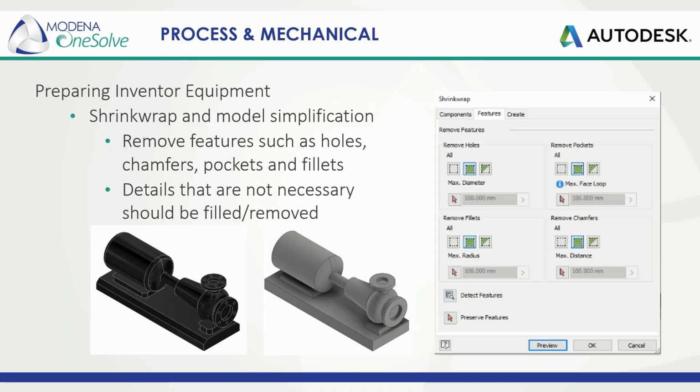Firstly, Plant 3D designers do not need fully detailed models. In fact, providing them with such models not only creates unusable file sizes, but includes a face count and complexity that would make the plant model struggle. Multiple instances would then further compound the problem.